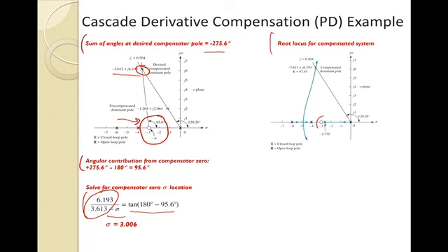So I have my compensator zero, and with my compensated system where the dominant poles are located, this would actually be sort of what the root locus looks like. So again, what happens is this pole at 0 originally goes to the left, so all poles trend to zeros, whether they're finite or infinite. In this case, I have a finite zero, so that pole is migrating to the left. Now these two poles, as I increase my gain, come together, go off axis, and then they have to go off to these zeros at infinity. So you'll see there's a zero here and then down here as well.